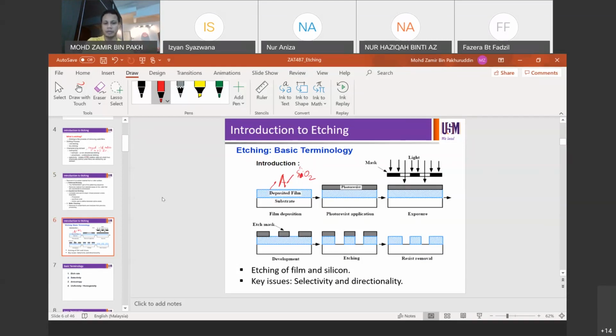So after your CAD, you're going to be left with this feature, up to what we have learned before. So you have got your mask, you've got your resist features on the wafer, and then under the resist, you've got your blanket SiO2, for example, and then done. So next, you've done your lithography here. Let's say you do oxidation. So this one is all lithography. And now you're going to do your etching here.